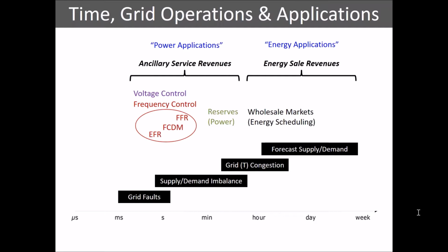There's one other acronym on there that I don't think I mentioned, which is FCDM. That's Frequency Control by Demand Management. Now that's important. It's a UK acronym, but the same kind of thing will appear under different names in different countries. The importance of that is that whereas in the past we've tended to focus on changing supply to cope with all these supply-demand imbalance problems, that's by definition demand management. It's recognising that demand flexibility is going to be important going forwards to solving some of these grid problems.